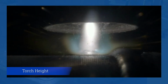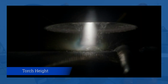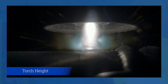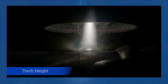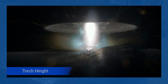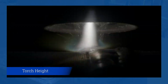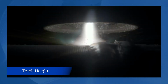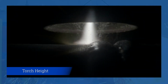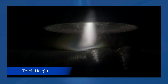We're also losing some shielding gas. This is something you have to set with your eye. When you have it set properly, you have the maximum powder retention rate, which also creates more consistent weld volumes, more consistent weld size. So this really is a critical variable. And once you determine what the height should be, then you check the voltage. So let's go the other way now. We're going to crowd the arc, okay? Now at this point, the powder columns are hitting on the outside of the weld. Same thing, we're losing too much powder. This is not set properly. We'll bring it back up to the way it's supposed to be.